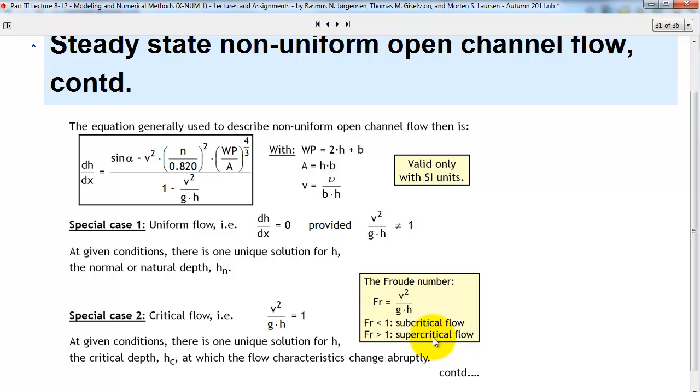So that will really result in that the depth can change fast. And that is, for example, if water is coming into the channel with a very high speed and a low height, then the friction will slow down the water, and then the depth will increase, and you will lose energy due to turbulence.